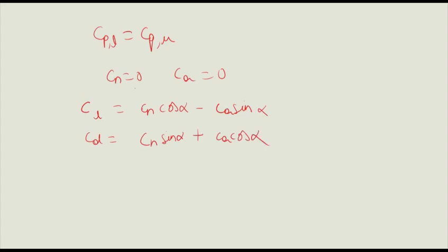So when we are saying Cn and Ca are 0, which in turn gives me that Cl and CD are 0. Hence, with the help of integrands and force and moment equations also, theoretically we are showing that the coefficient of lift and drag are 0, which in turn means that the lift and drag are 0 over here. But this is the case for an inviscid incompressible irrotational flow. So this is it about non-lifting flow over a cylinder. Thank you for listening. Stay tuned.